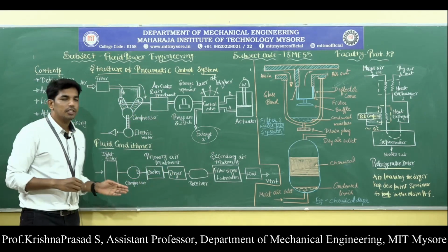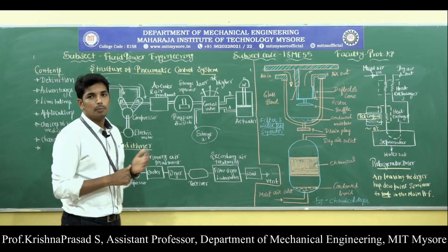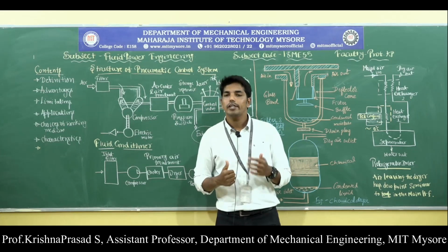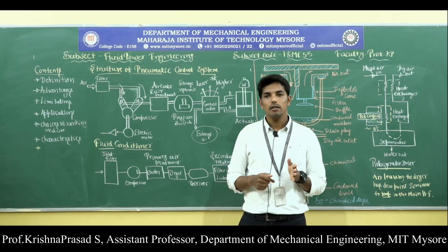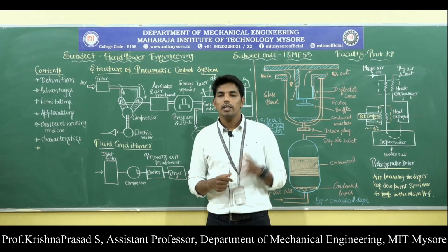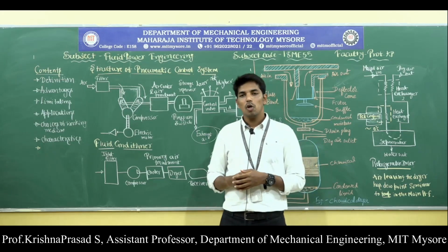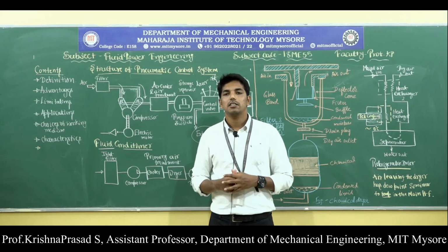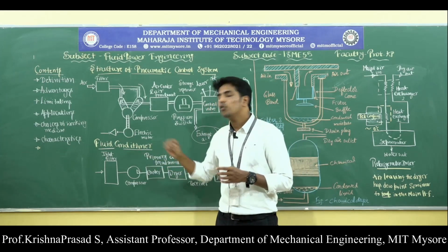Then, a very important one: what is meant by fluid conditioner? Fluid conditioner and the preparation of compressed air are one and the same. We all know that the compressed air or fluid used in a pneumatic system should be clean and dry. That means it should not contain any contaminants like dust, dirt, oil, and water vapor. Atmospheric air mainly consists of smoke, dust, and dirt. These should be removed before the air is put to use, because they will cause problems in the components of the pneumatic system. So the preparation or treatment of compressed air is called the fluid conditioner.